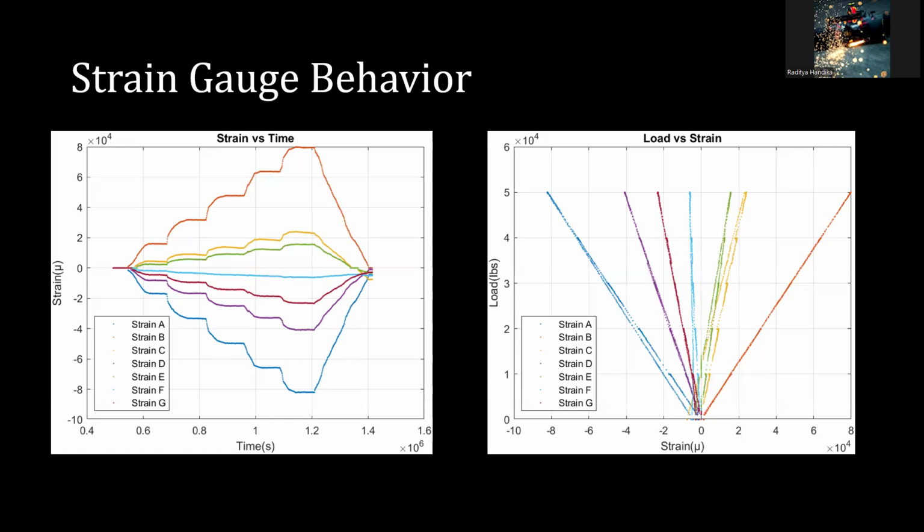Uniaxial strain gauge A and B reveal normal strain, while strain gauge C and D record both normal and shear strain based on the position. On the other hand, the triaxial strain gauge, which consists of three uniaxial strain gauges, primarily measures shear strain. This is because at the center of the beam, no normal strain occurs, but maximum shear strain is present. Thus, triaxial strain gauges are required to measure the strain in the shearing direction.